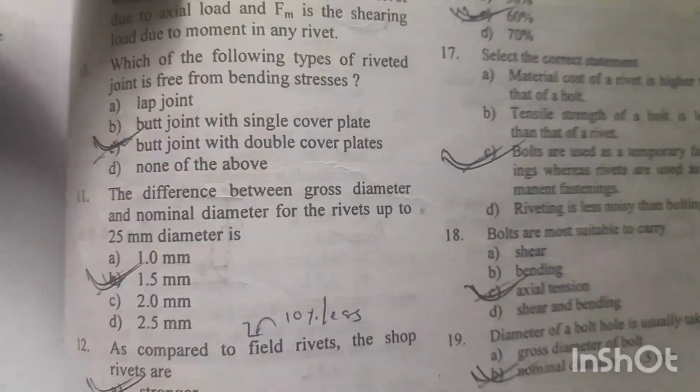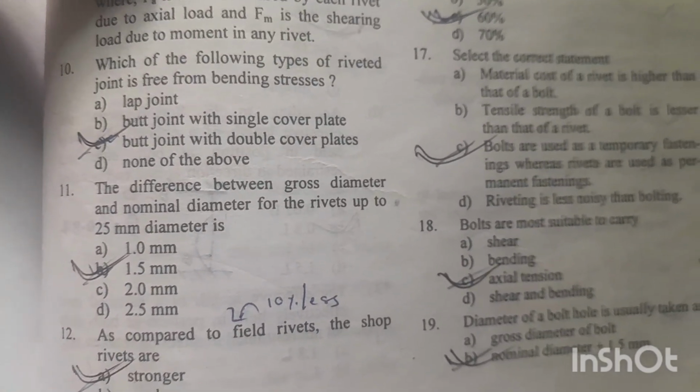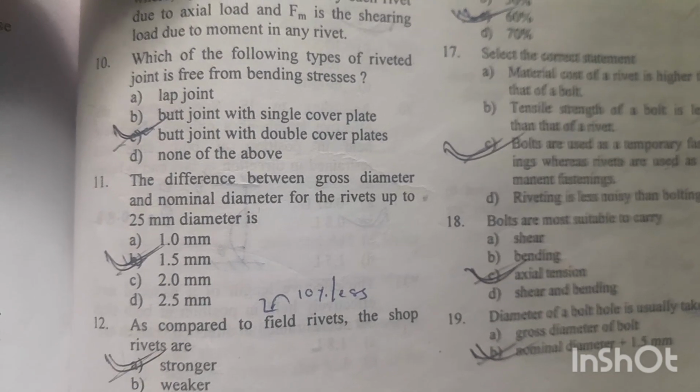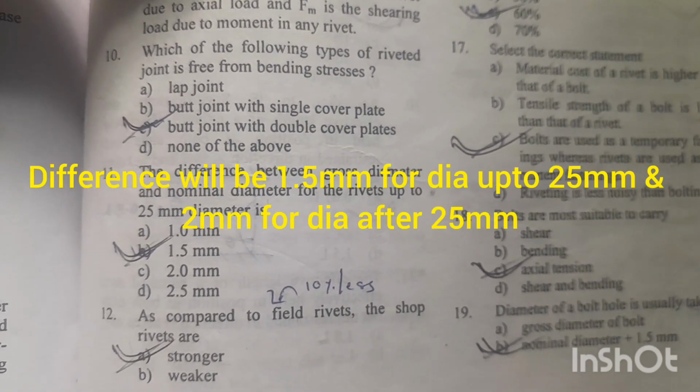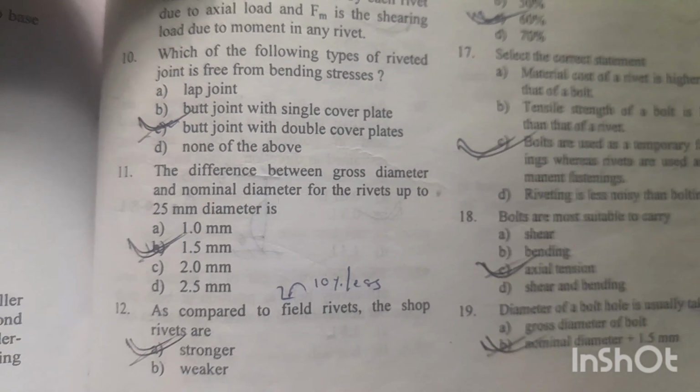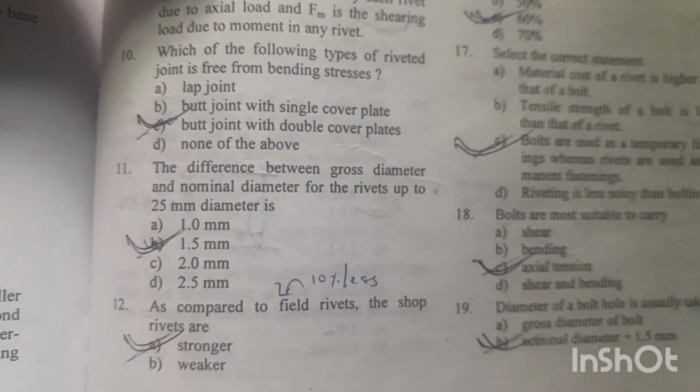Question number 11. The difference between gross diameter and nominal diameter for rivets up to 25 mm diameter is 1.5 mm. And if the diameter of the rivet is greater than 25 mm, the difference will be 2 mm. Question number 12.